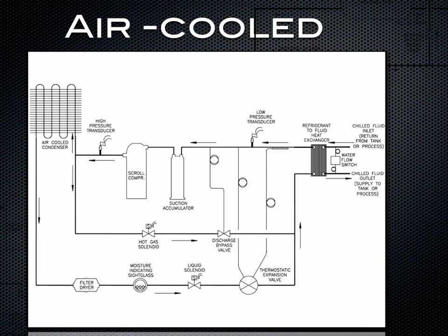There's a video that I posted called the processed water side of a chiller. And in that video, I stated a piece of equipment will generate heat. The heat will be transferred to the water, and that water or water glycol will come directly to the chiller evaporator, which is this piece right here. The chiller evaporator is where the processed water side and the refrigerant side meet, and the heat is transferred.